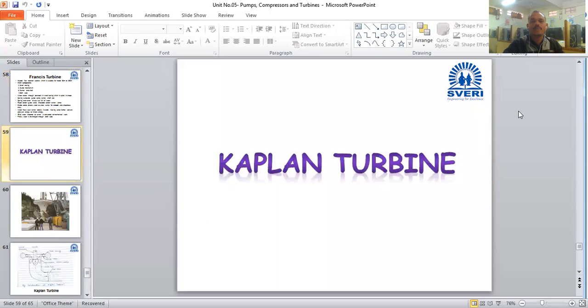Now next one is the Kaplan turbine. This one is the last turbine from our syllabus. Generally these turbines are used in hydroelectric power plants. Now, when can we use the Kaplan turbine? Whenever the head of water is very low, near about 50 meters, or from 20 to 50. There is a range, as the head may change, and we can use the Kaplan turbine up to that range, where the discharge is more. Compared to the other turbines, the Kaplan turbine has lower efficiency.